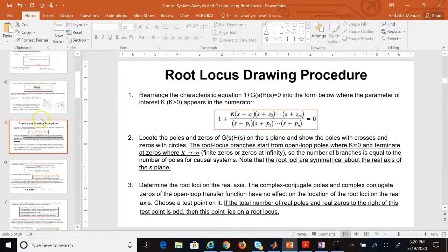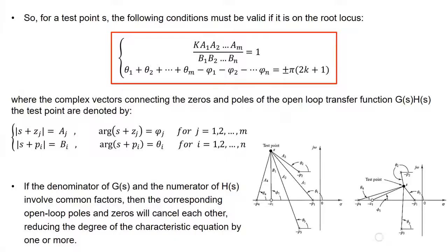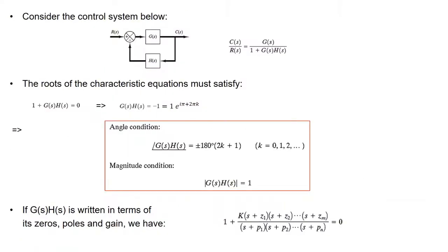And one last thing, you might wonder why these points are negative z's and negative p's. Didn't you say that z's and p's are the zeros and the poles of the transfer function? No, I said z's and p's are the zeros and poles of G(s), but with a negative sign, right? If you look at these, all of these terms are positive instead of negative.